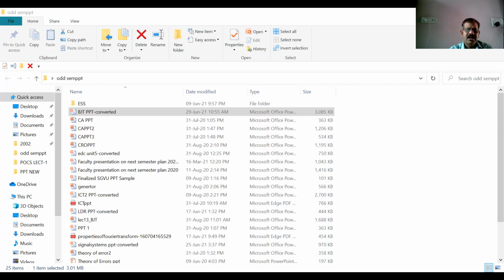Here, the base current amplification factor beta in common emitter connections. In common emitter connections, the input current is the base current and the output current is the collector current. So the ratio of change in collector current to change in base current is known as the base current amplification factor beta.